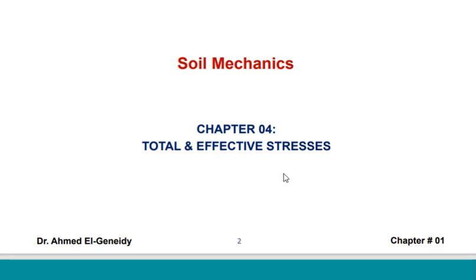But this stress is going to the soil. The soil is not only soil, it includes soil and includes water. So maybe water is trapped below and it does not have the ability to move. In this case, it will carry some of the weight of the building. Some of the weight of the building will go to the water. The rest will go to the soil and will affect the soil. How can water carry load?